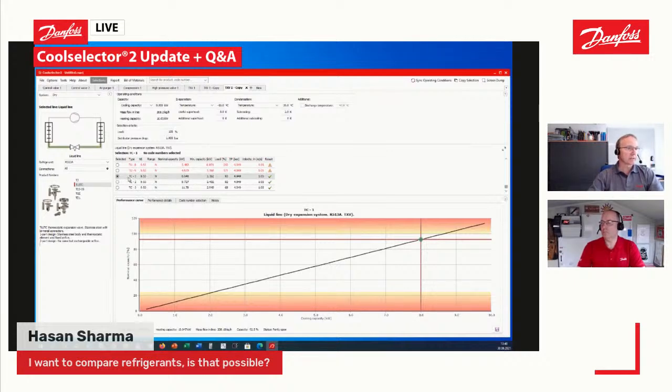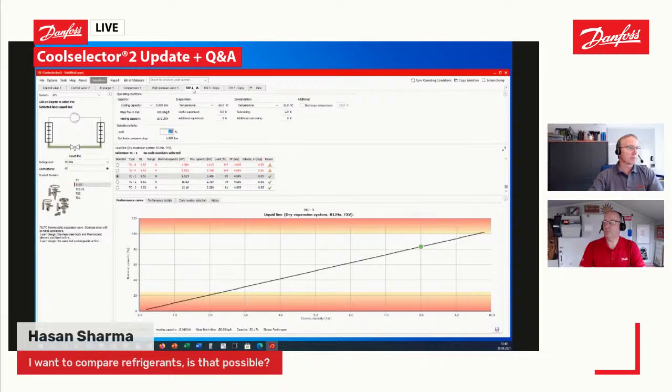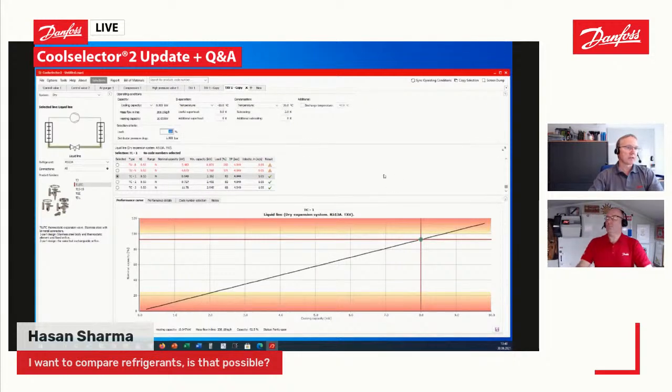So here I get the same orifice, so that's already good information, with the capacity of 8.65. And before, using 134A, it was 9.6. So the capacity is a little bit lower than before if I go to the new refrigerant. This is a one-to-one step approach, comparing one component directly to the same component with another refrigerant.